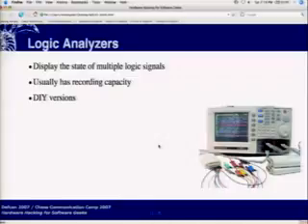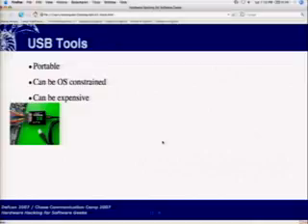You can make a do-it-yourself logic analyzer. I also have kits for that. Since we have the question and answer room, I'll be giving some of these kits out there. They hook up to the parallel port and can watch 8 lines at once. Due to the relative slowness of the parallel port, they get about 1 million samples per second, so they can't pick up a signal much more than 1 megahertz. Well, actually it has to be much less than 1 megahertz, for those of you familiar with, I believe, Shannon entropy. But on the other hand, it's cheap.